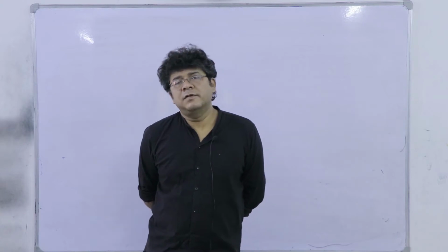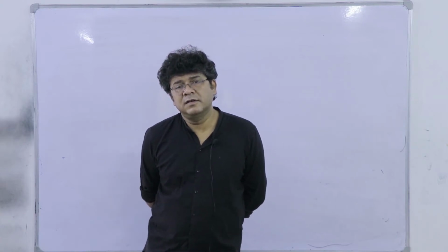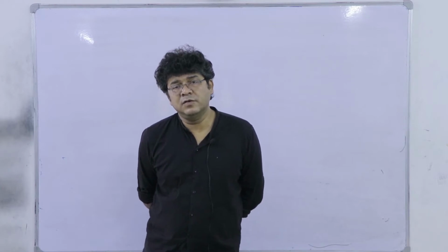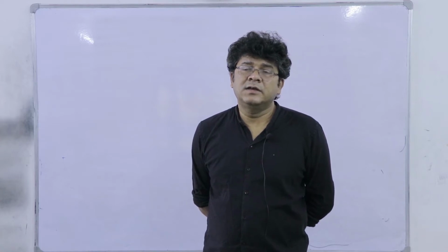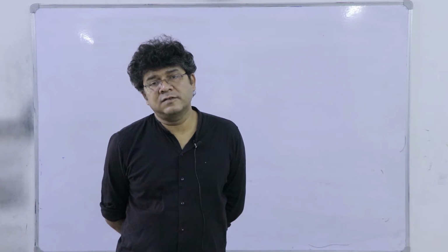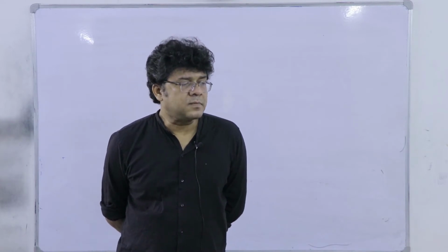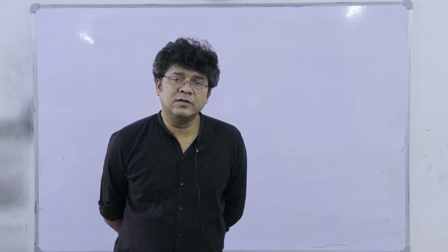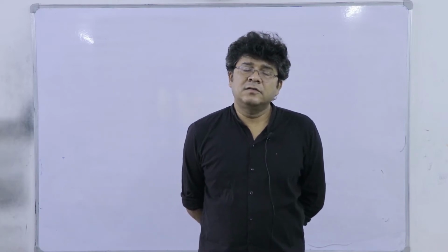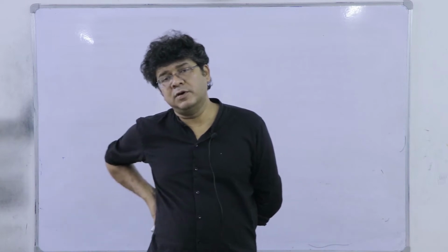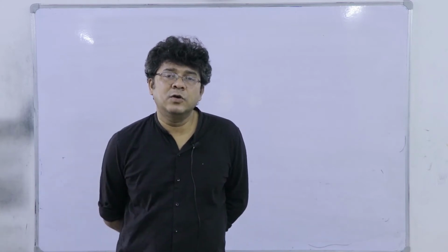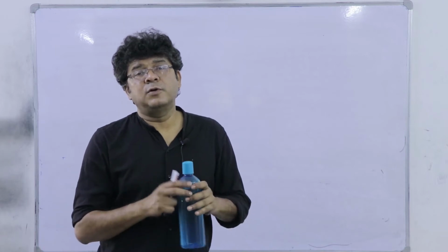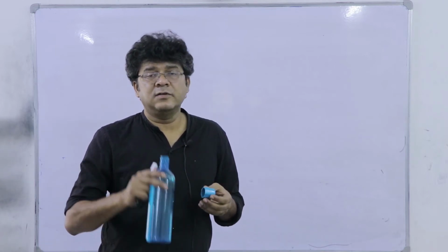From there we introduced the concept of the Thiele modulus and derived the relation between the effectiveness ratio and the Thiele modulus, where the effectiveness ratio is the rate of the reaction with pore diffusion divided by the rate of the reaction without pore diffusion, that is, if the reaction continued with the external surface concentration of the reactant. So if pore diffusion has no effect, then epsilon, the effectiveness factor, will be equal to 1, and in a strong pore diffusion regime, epsilon is nearly equal to 1 by MT.